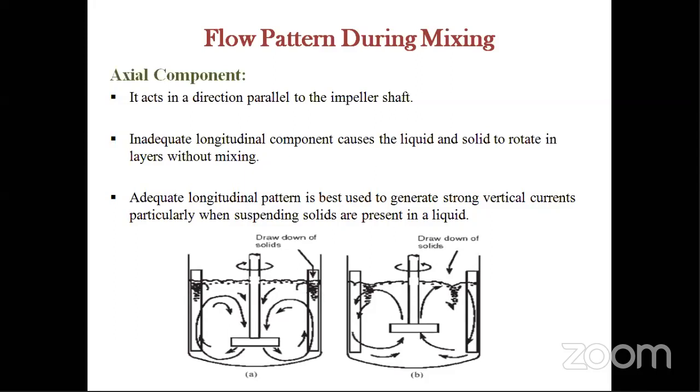So you have to maintain the most optimized speed. That time the axial flow happens, and it does not let the solid particles settle at the bottom of the tank. Now when they have settled, you increase the speed again. What happens?